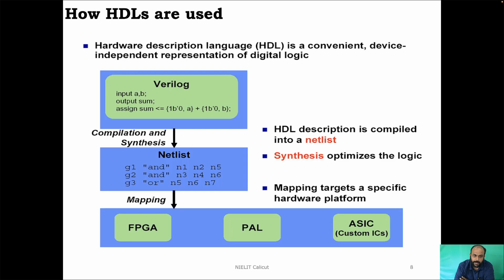So when we are writing a Verilog program, we have to write it with the mentality that we are writing it ultimately to convert it to hardware. That is called RTL designing. There is a difference between RTL designing and behavioral designing. RTL stands for register transfer level. By that, what is meant is writing a Verilog description of a hardware in such a way that it can be converted to a structural equivalent by the process called synthesis.